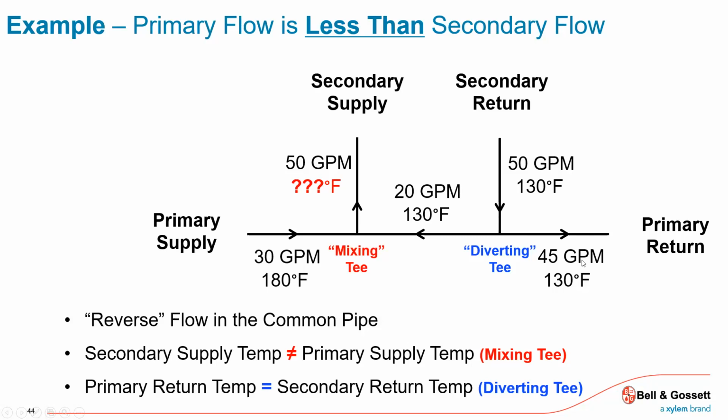I can use that. If I have a multiple boiler plant and on a really light load, I have 3 boilers off and 1 running, and I have a distribution main that's maybe pumping at that design flow, I'm mixing a little bit of hot water from 1 boiler and the other 3 are off. Between the return temperature and this hot boiler, I get a mix.